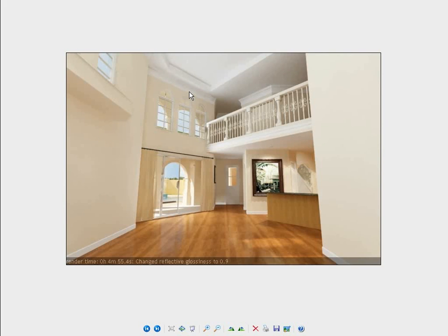When I render with these settings, my render goes from this to this. And this is a great improvement. Fairly nice quality, a lot more detail brought out, especially in the windows. Plenty of detail pretty much everywhere. There's definitely still some noise on the second floor ceiling, and as long as my GI settings are decent, I can be confident that the ceiling, which is the area that needs most improvement, can be improved with image sampling.